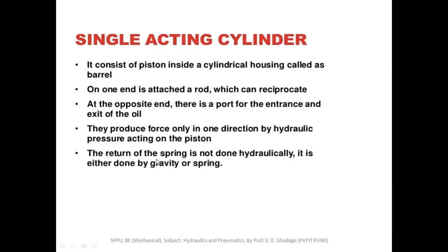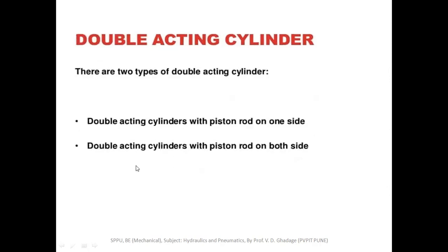The return of the piston is not done hydraulically. It is either done by gravity or spring. Double acting cylinder. There are two types of double acting cylinder: double acting cylinder with piston rod on one side, and double acting cylinder with piston rod on both sides.